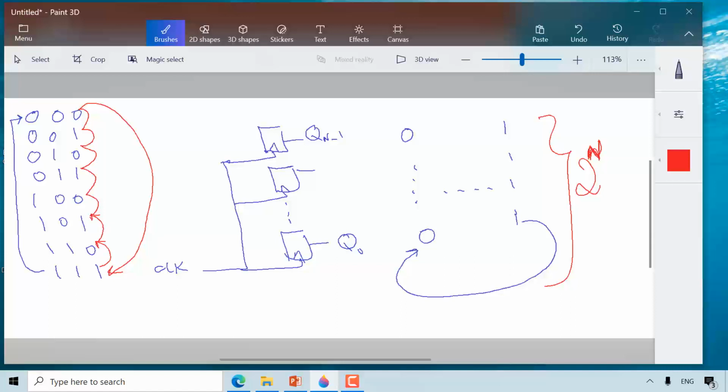Of course, before I go back to the lecture, we have here the logic where we update whatever flip-flop I have, the D or T flip-flop. In digital logic class, you studied the T flip-flop, JK flip-flop and D flip-flop. Honestly, nobody uses the T flip-flop and the JK flip-flop in practice.